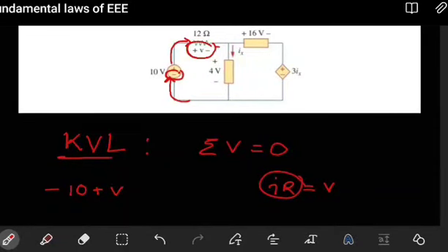When we continue, we find this resistor, and we find that circuit element positive first. Here as well, we're not given the resistance value. Instead, we're given the potential drop there, so we go with that potential drop. No need for us to have IR. So we go with plus the potential drop. Since this is the last circuit element in this loop, we end there and say this has to equal